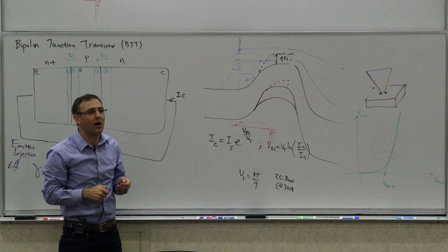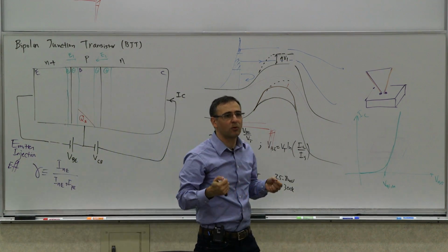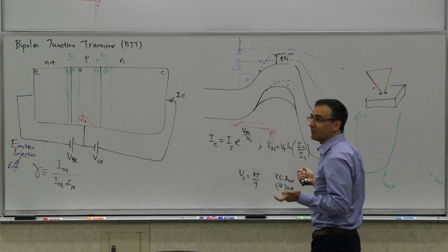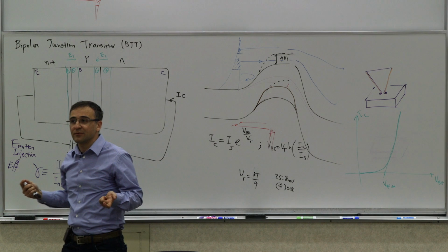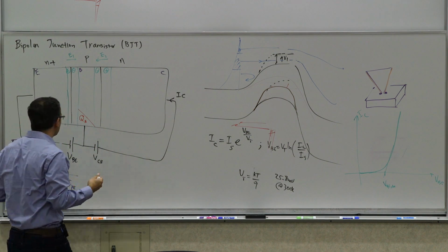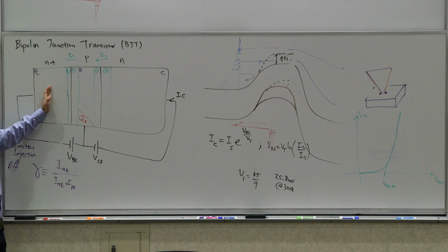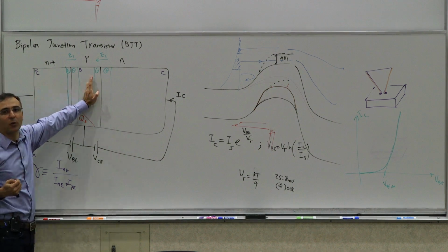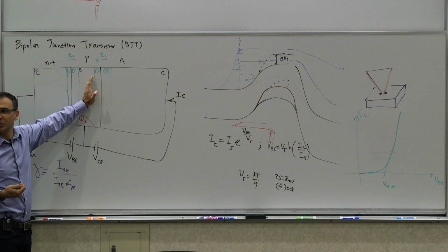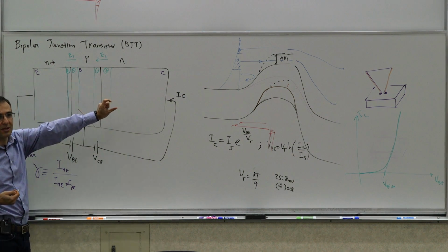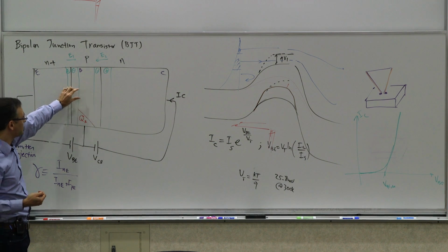And this is the basic of what we call heterojunction bipolar transistors, or HBTs, that are used extensively for very high frequency applications, particularly. So for example, silicon germanium transistors are like this. You have silicon, but then you have a silicon and germanium alloy in the base. And germanium having smaller band gap, the alloy will have a band gap that's determined by the ratio of the alloy. It will have a smaller band gap.